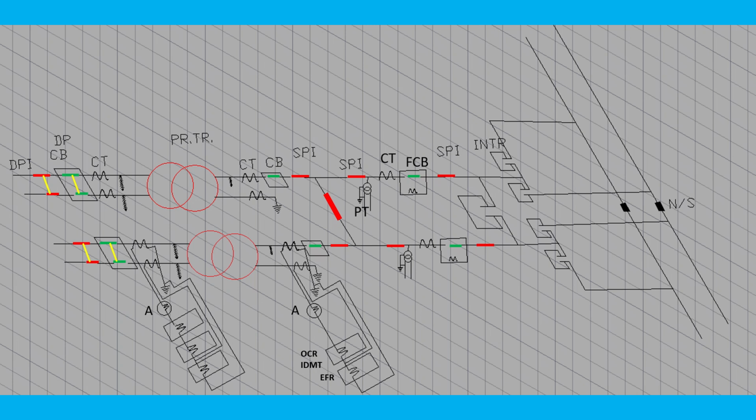So for protecting the power transformer, when the transformer protection relay operates, it will open both the CBs, both sides. One is a double pole circuit breaker, another is a single pole one. Feeding side is not feeding transformer. Outgoing side is a CB, it is single pole, but for incoming it is double pole. Both the CBs will trip to protect the transformer.